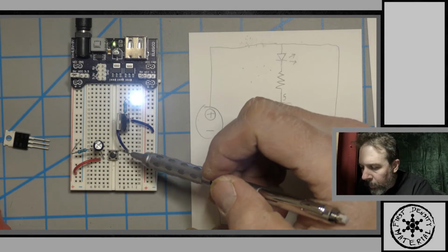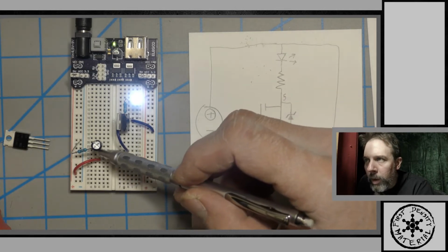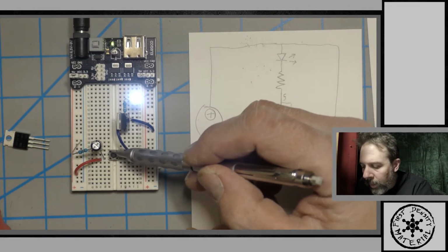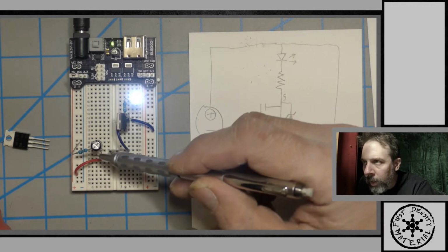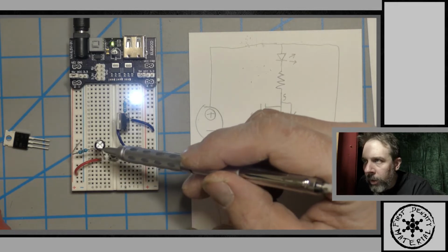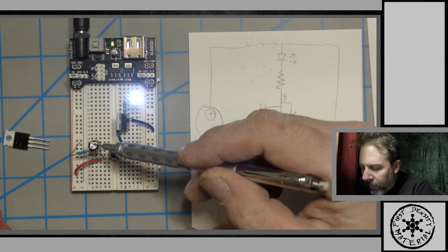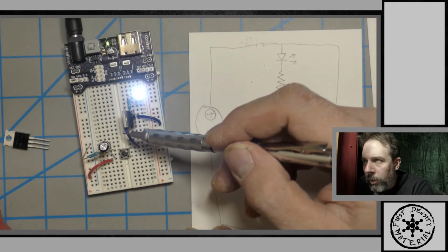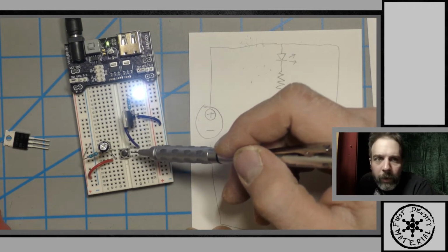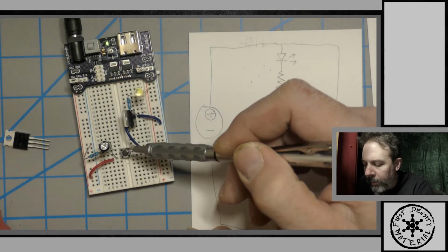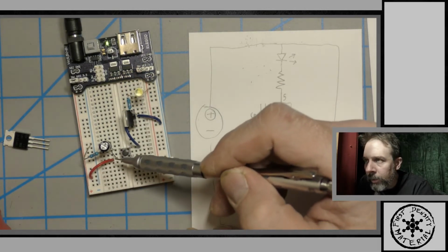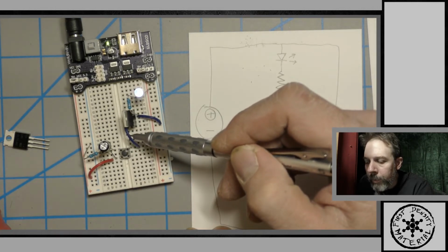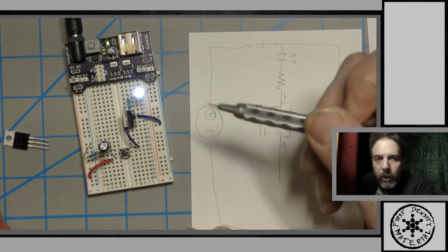And now we have to deal with this switch. The switch is kind of complex in a way because we know that this area right here is all hooked together. So you're looking at a resistor, you're looking at the negative leg of a capacitor, all being hooked into the gate even before the little thing is switched. Okay, and by clicking this, that's making this positive, going in and hitting the gate. Therefore, turn the LED off.